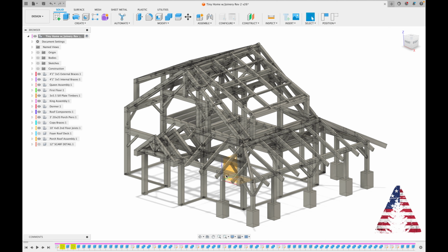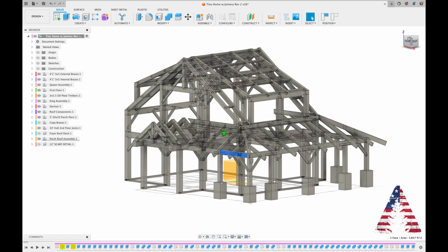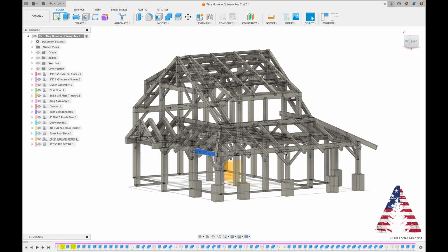I'm utilizing some splines inside of these posts to tie these beams together. You can see the splines inside. Those will be pegged, and then braces through there. So this should go together pretty easy. And my rafters just set on top of this beam to tie all that together, square and true it up. And all of those set on these piers that'll be concrete with a stone cap, some blocks and a stone cap. So they're 20 by 20, they're 3 foot tall. Then my 8 by 8 posts will set on top of those.